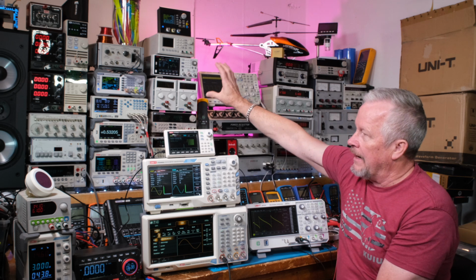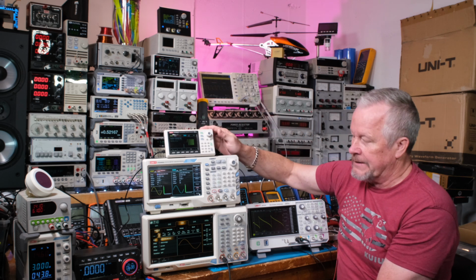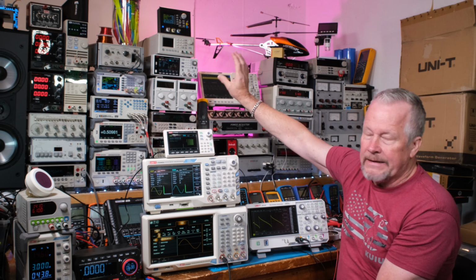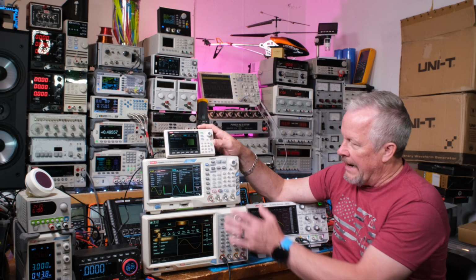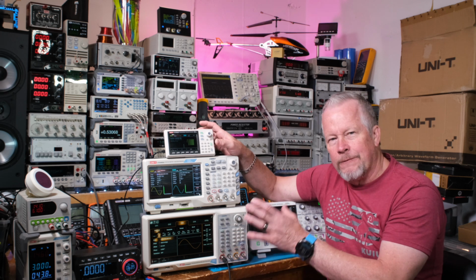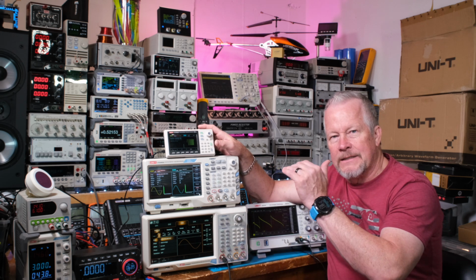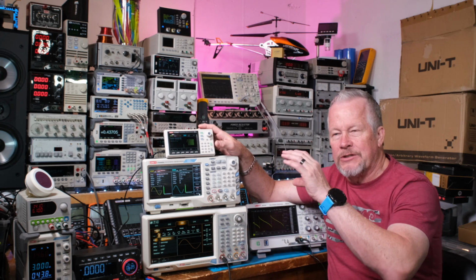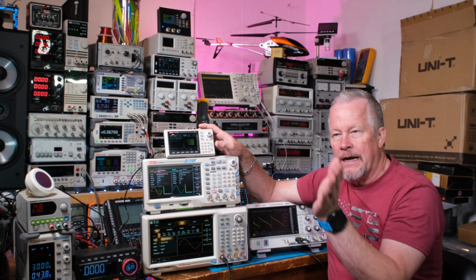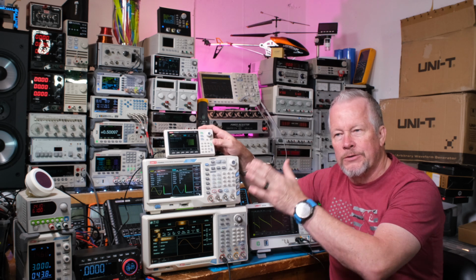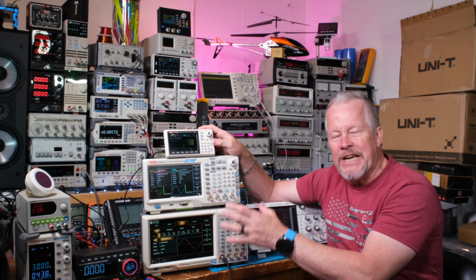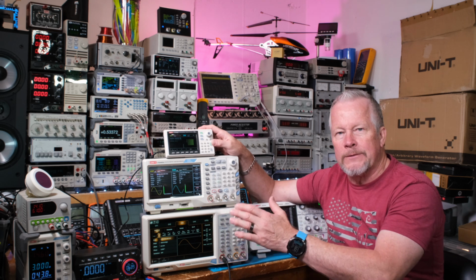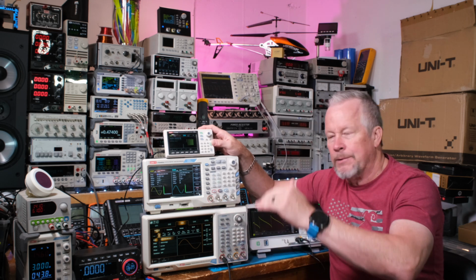He can go that higher voltage for twice the frequency. But above 20 meg, he's limited to about half that volts. Okay, so the volts drop in half. Now, with these two, you really have to look at the data sheet, because instead of just saying at this frequency you get higher or lower voltage, with these two it changes through the frequency range. So it kind of starts to drop, okay?